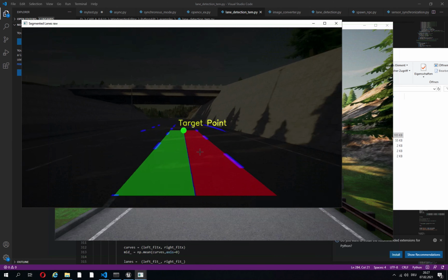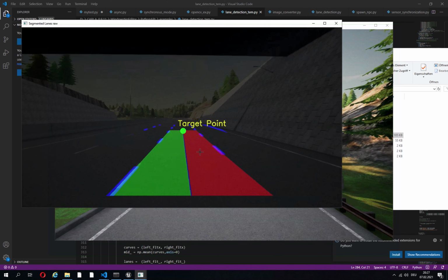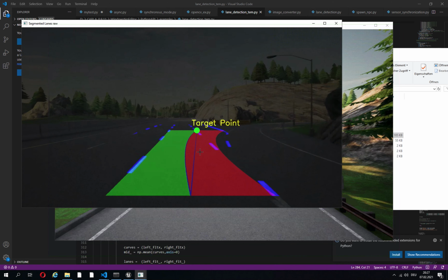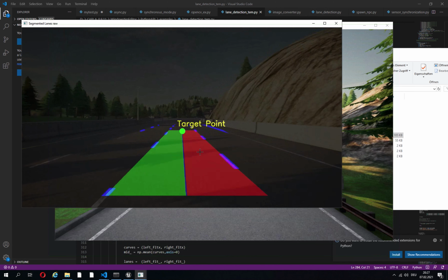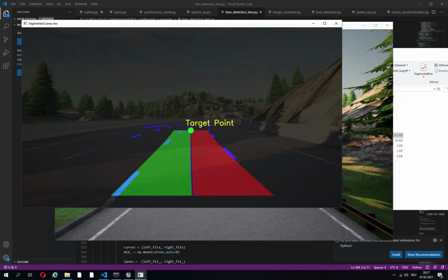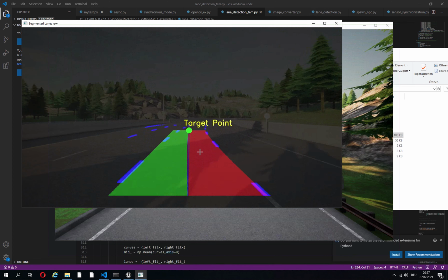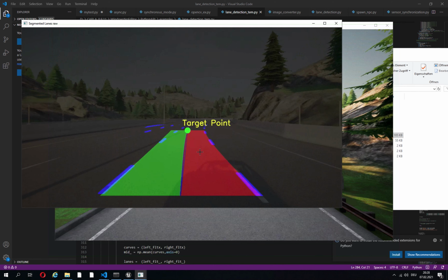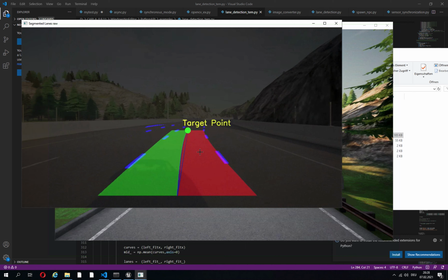You can see it now, that happens here. And this, for example, is where the controller comes in. In general, if you remember, in the beginning we talked about PID controllers, and you can also design these PID controllers in a way that they don't react that fast, especially with the proportional gain. If we try to reduce it, then of course the response will not be that fast to such sharp changes. So there are different ways, including the controller itself, and including if we are using a machine learning or deep learning based controller.